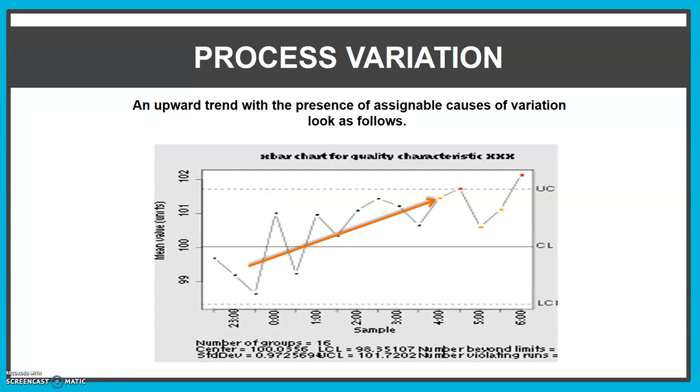If you get a control chart like this, that means still under control, only one point is an outlier. Only one point is an outlier here. Please bear in mind, if the trend is getting higher and higher, that means it is heading toward the outlier trend, please do the improvement to reduce it.